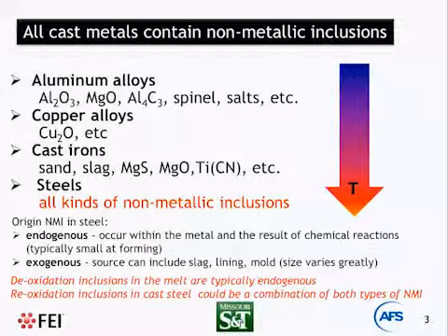Before that, let me briefly discuss why we have steel casting quality problems caused by non-metallic inclusions. Castings from all alloys have more or less non-metallic inclusions. For example, in aluminum alloys, non-metallic inclusions present as aluminum oxide, which could have the shape of an individual particle or create films, even bifilms. Some exogenous inclusions come from flux. In copper alloys, non-metallic inclusions mainly present as copper oxide.